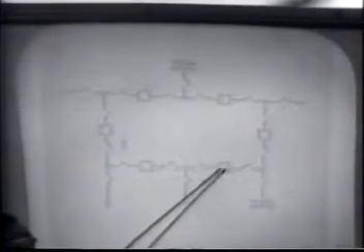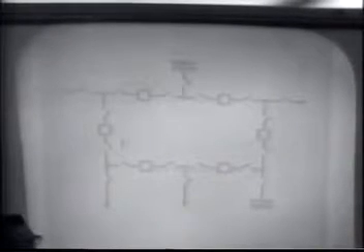This gets you additional flexibility with only a slightly greater cost than the other system, that you have the same number of breakers, which is the expensive element. You do add to the complexity of your auxiliary circuits in that you will have to parallel current circuits from breakers on either side of a line or transformer to perform your relaying and metering.